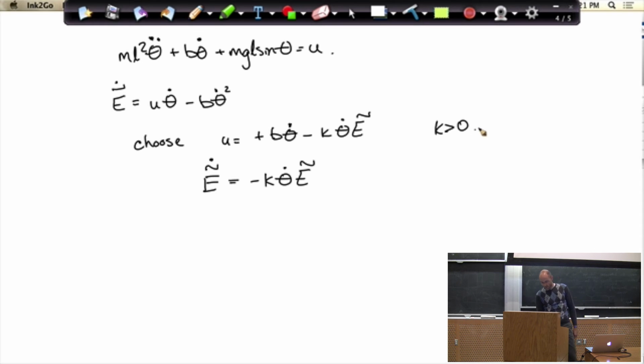Okay, and if you want to make this dynamics true, even though you had some damping in the original system, then that same recipe tells you to run the same controller I did with the undamped system, but also actively cancel out the damping in the system. So apply some torque that counters the damping torque in the system.